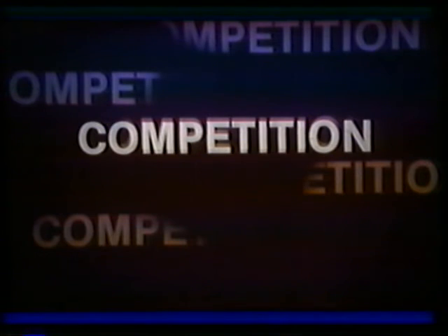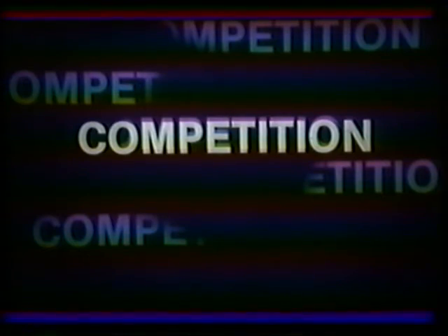The valve insert seats which contact the valve face must be matched in hardness with the mating face. For this reason, they are usually manufactured from a high hardness material. As with other engine overhaul replacement parts, competition in valves, springs, guides, and valve seats is fierce. Imperial Cleveite, IPD, TRW, Eaton, and Federal Mogul, among others, sell these parts which will fit our engines.